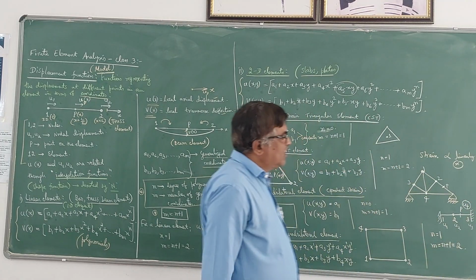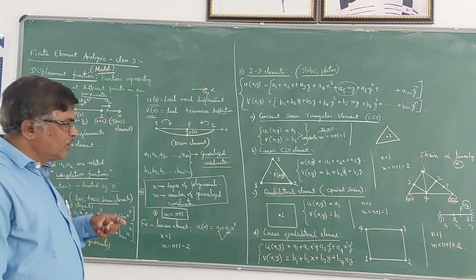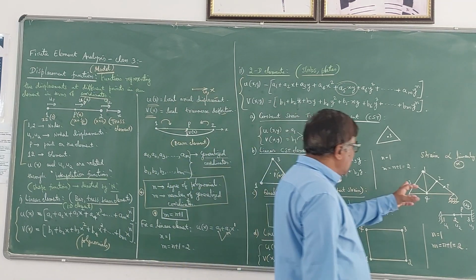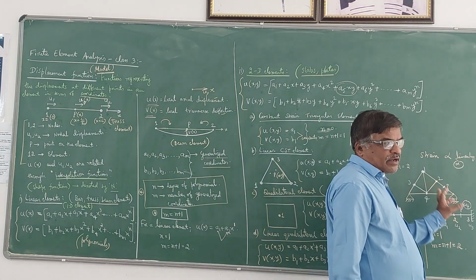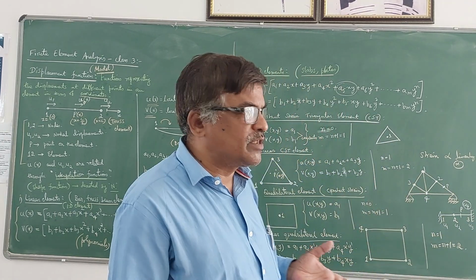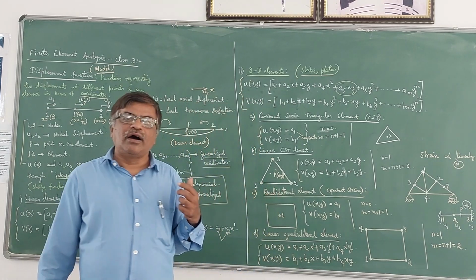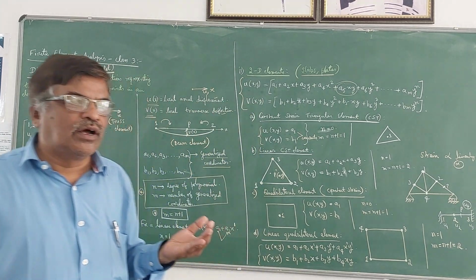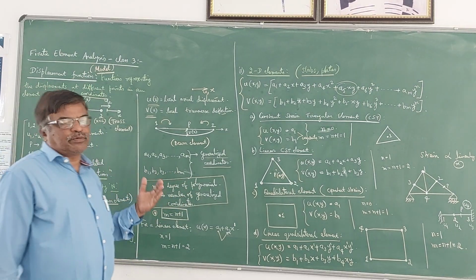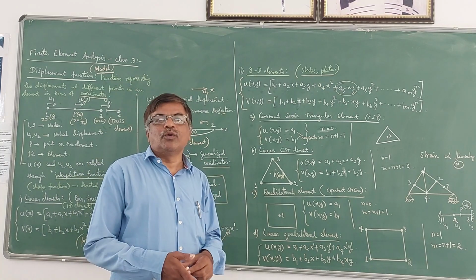So this is how the shape function or interpolation function is useful in finite element analysis. In matrix method of analysis, we are going to find the nodal displacements. In the next step, if you want the displacement value at some other point, then we have to develop the shape functions. Using those shape functions, depending on the type of the element, we can always obtain the displacement at the required point by knowing the coordinates of the point.